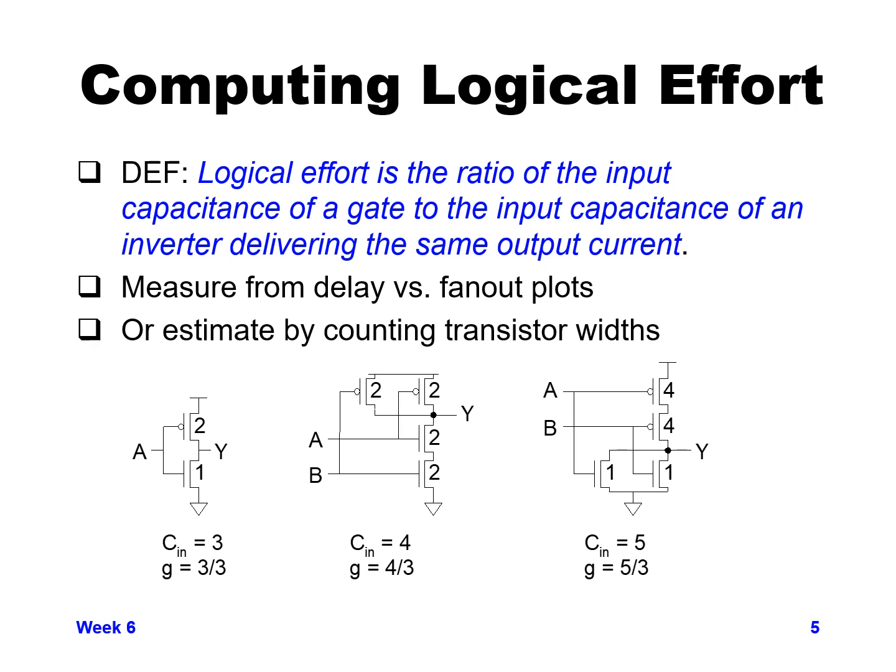Now when we look at a NOR gate, on the other hand, your NMOS are in parallel with each other, so there's a single NMOS between your output and ground, so they stay the same size as a basic inverter, size 1.